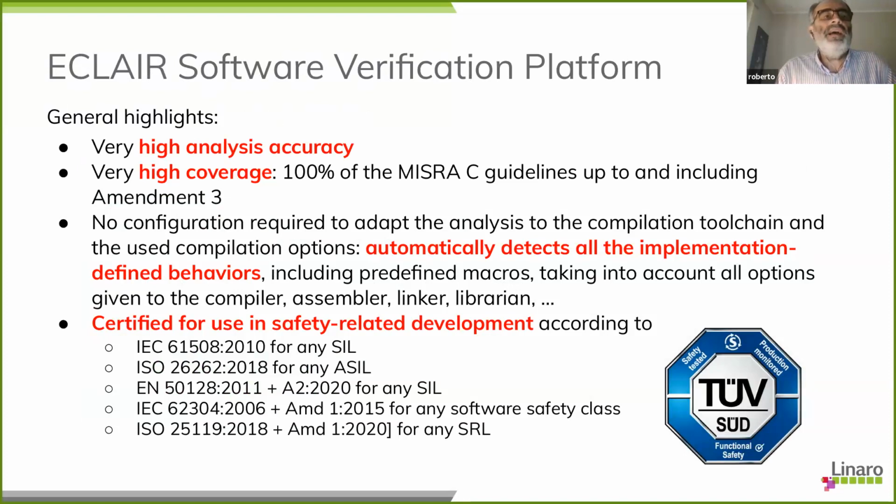The general highlights: it has a very high analysis accuracy. So in the trade-off between speed of execution and accuracy, we have favored accuracy. We have very high coverage. We cover 100% of the MISRA C guidelines up to and including Amendment 3. Amendment 4 has just been published and the implementation of the checkers is underway.